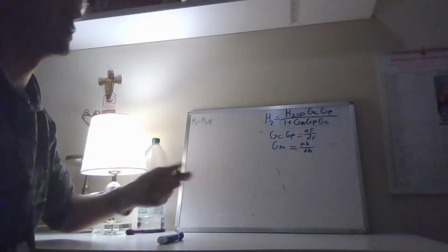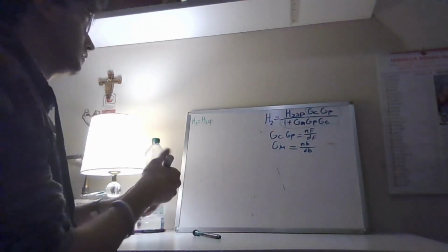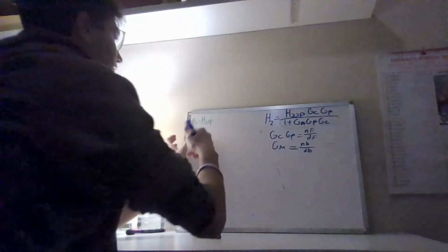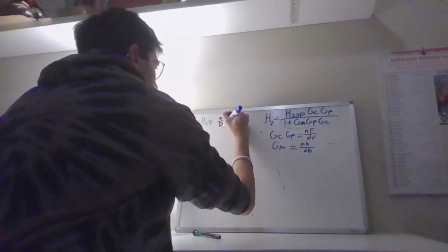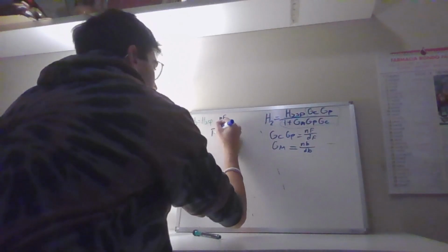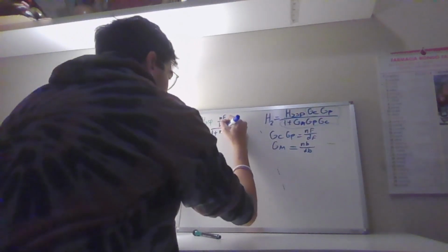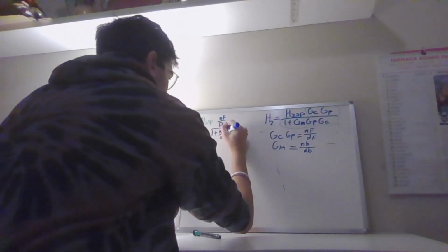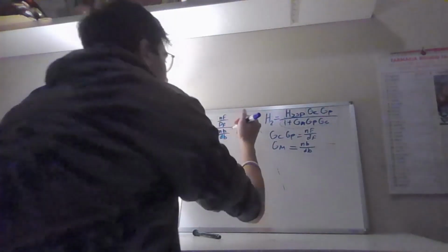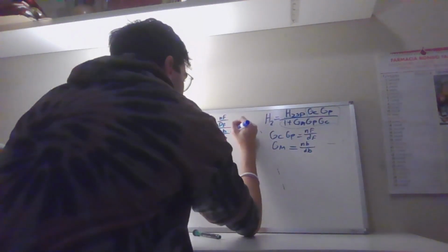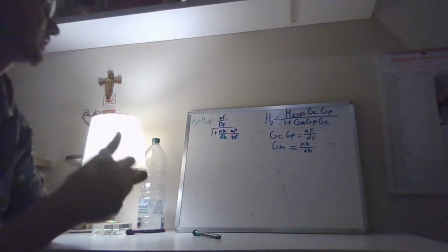And just imagine that we're bringing this all the way down throughout. But now I'm just going to be solving for that side and simplifying it down a little bit. So if we plug this in, this will have our numerator forward and denominator forward over 1 plus GM, which is numerator backwards over denominator backwards, multiplied by GCGP, because that's in our denominator as well. So NF and DF for numerator forward and denominator forward, right?